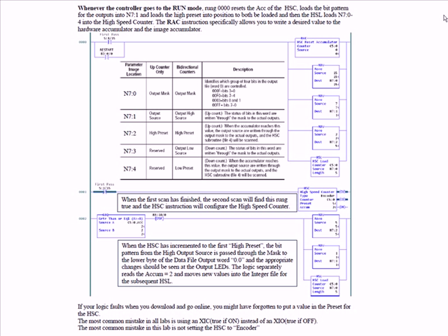So the high-speed counter accumulate register, when applied as a high-speed counter, is not going to be equal to the accumulate register in C50 at all times. The C50 accumulate register will update from the register that's actually in the high-speed counter, the electronic one.